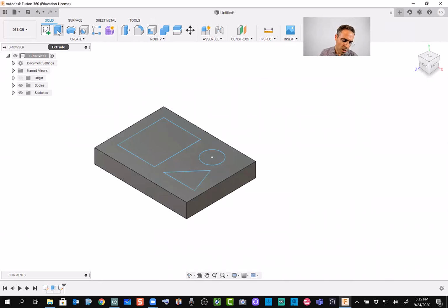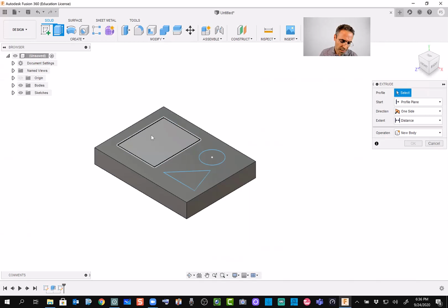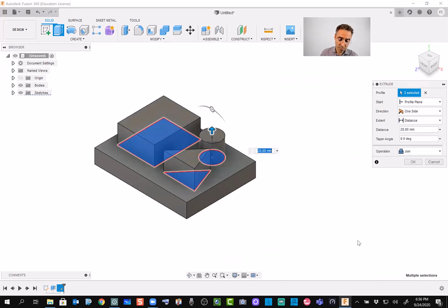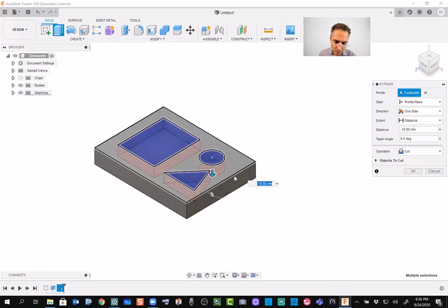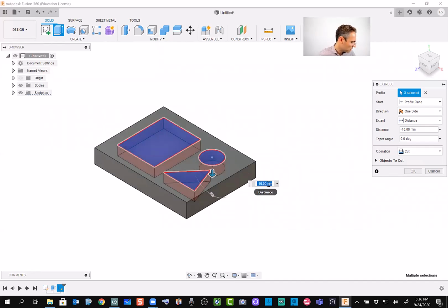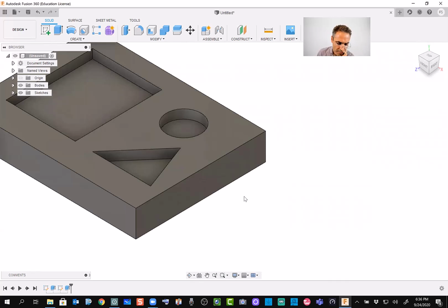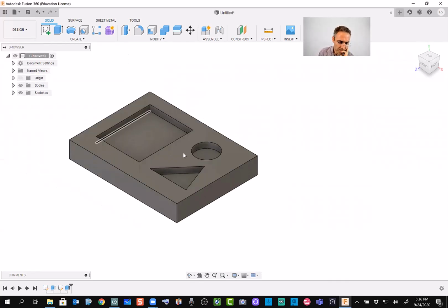And now this time, again, we select Extrude, the one on the top, and we select this area that we just created, all right? These three. If I move them up, it means I'm extruding them up, but I'm going to create a pocket. So instead of having a positive number, I can just push these things down, so you see it becomes red, or here I can just enter minus maybe 5 millimeters, all right? So that's the pocket that I created, 3 random shapes.